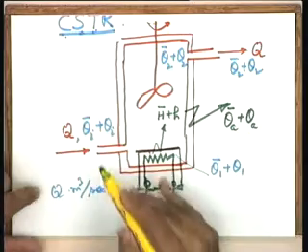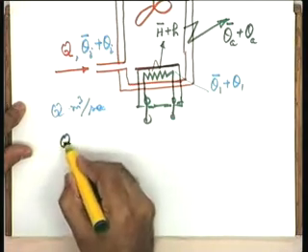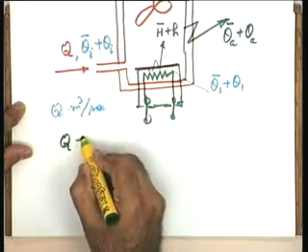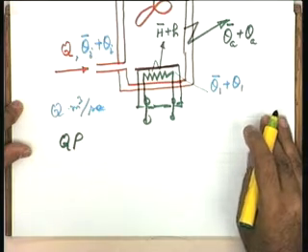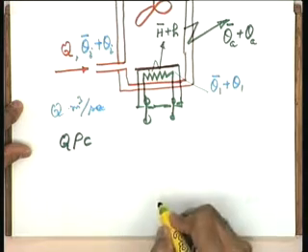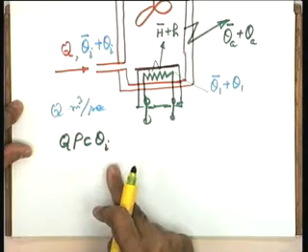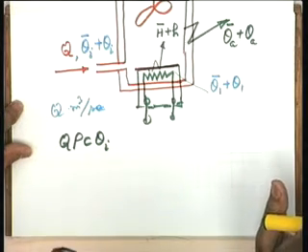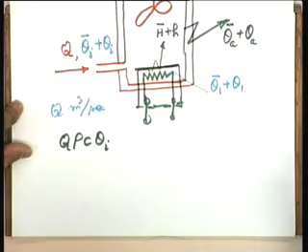So, help me please now, what is the heat inflow? Look at this now, at this point Q is the Q meter squared per second, rho is the density, becomes kilograms per second, into specific heat C into theta I. Note that I am not directly writing the perturbation variable, I will save my effort and I will avoid writing theta I bar again and again.